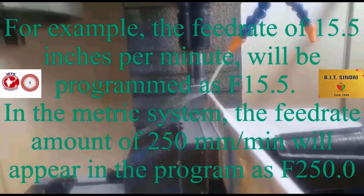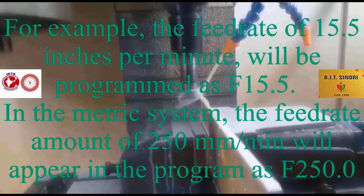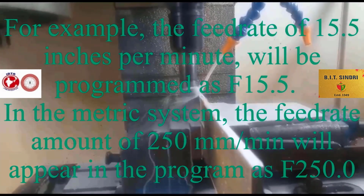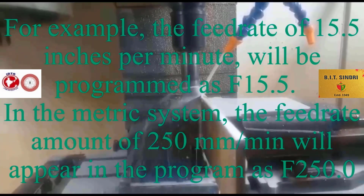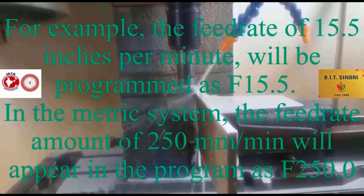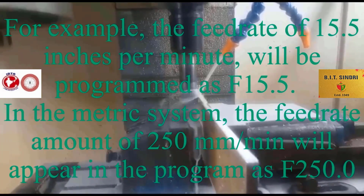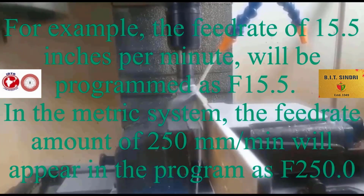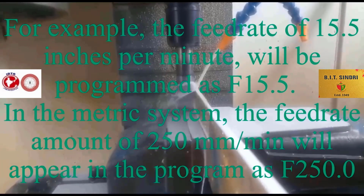In the metric system, the feed rate amount of 250 mm per minute will appear in the program as F250.0. A slightly different programming format may be expected for a special machine design. One important item to remember about feed rate is the range of the available feed rate value. The feed rate range of the control system always exceeds that of the machine servo system.